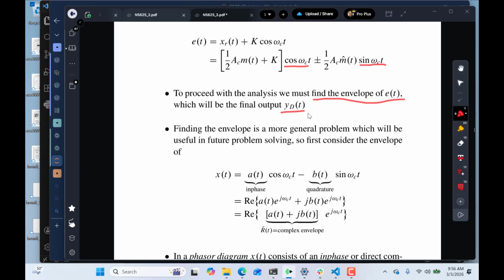So this is a little bit of a game, but this is getting us into some complex signal modeling. When I say complex, I mean complex arithmetic. So what we can do is replace the cosine by an e to the j, and then we're going to take the real part of it, so we'll get back that cosine. In here we'll put in a j e to the j, so that if I take j e to the j and take the real part of that, I'm going to get back a sine.